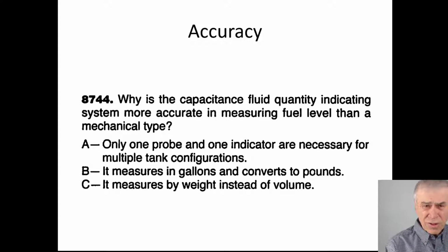B, it measures in gallons and converts to pounds. Well, the capacitance doesn't do any converting. It basically measures in pounds. It measures the mass, the thickness of the fuel that is acting as the dielectric. So that's the opposite of what that one's saying. So C, it measures by weight instead of volume.